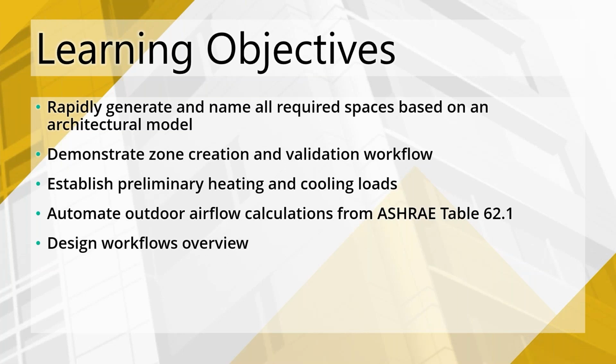We're going to talk about zone creation and the validation of space and zone association, making sure you understand the view templates associated in the MEP Productivity Pack so you know exactly how to leverage these views for the most optimal workflow. We're also going to talk about a couple of different ways you can establish preliminary heating and cooling loads, both inside Revit natively and externally, though I won't go through the external example live, I'll talk about it. We'll see how you could potentially do some external heating and cooling loads.